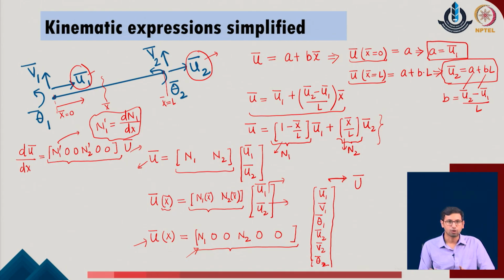So, with this idea now we are in a position to identify the standard variations of the given primary displacement values across the length of the member, which are described in terms of only the nodal values of the given system and the shape functions which are the function of the regular x parameter of the system. Similarly, one can also do it for the parameters v1, v2 and theta 1 and theta 2 in the given system, but while doing it for these, one must also remember that theta 1 and theta 2 are not independent values.